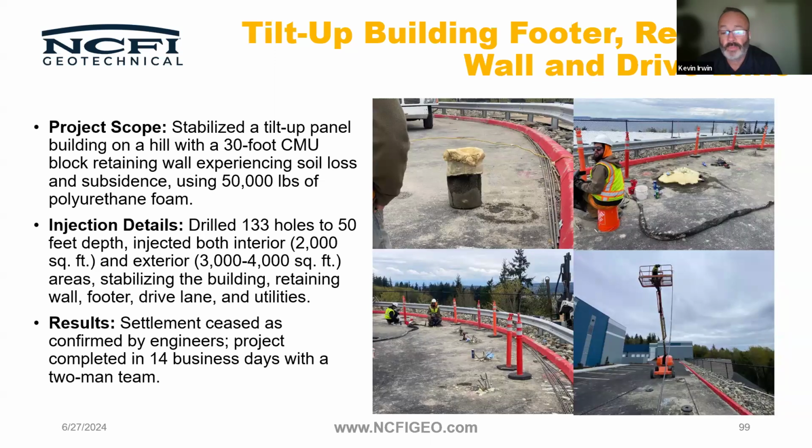I would make one comment that if you've got an active drive lane or roadway, you've got to get rid of those steel tubes for the first few inches, because the road is going to move and continue to move a little bit. Whether it settles or not is different, but those rods tend to work their way out and start cutting tires.